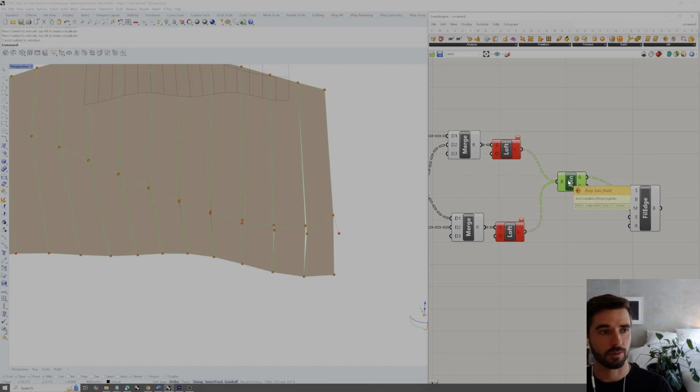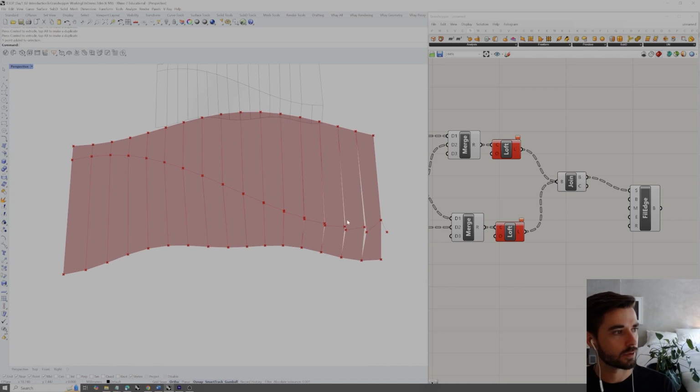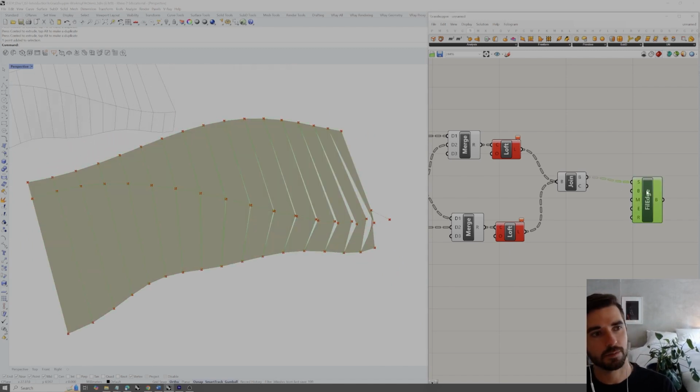If we don't want all of the list to join together, we tend to either leave unflattened or we tend to graft, meaning that each branch is going to be its own kind of object and iterated through individually. And this is really great for coordinating multiple lists where we need to iterate through individual panels or individual elements or items.